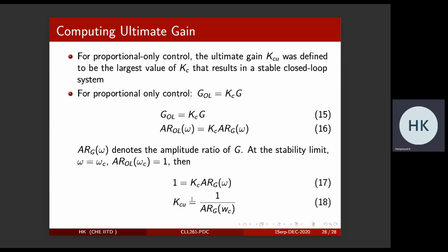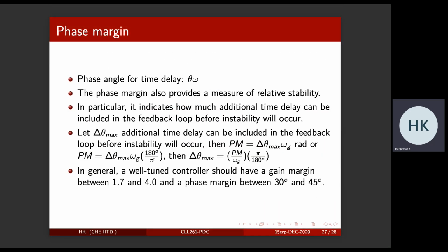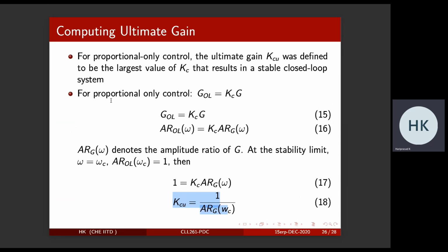So once you have Kcu, you will be able to use many of the controller design methods which were presented in the previous chapters to compute the controller details. So this is how to do the controller synthesis based on the gain margin.